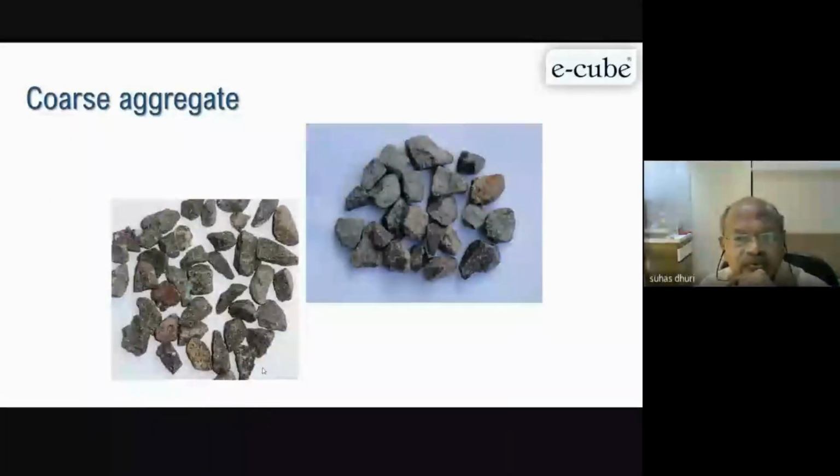Now see the coarse aggregate here. This is a very good aggregate. You can see the near angular shape. The peculiarity of angular shape is that surface area is minimal; volume to surface area is minimal. Here you can see the aggregates are elongated lengthwise. Now for the same size, the surface area is more. In a subsequent slide, I'll explain this, because this is very important when you are doing a mix design. Very, very important. This is one of the factors one has to understand very carefully.